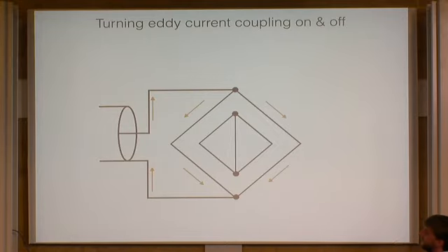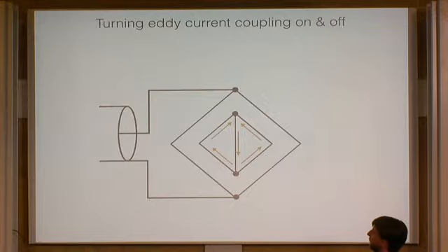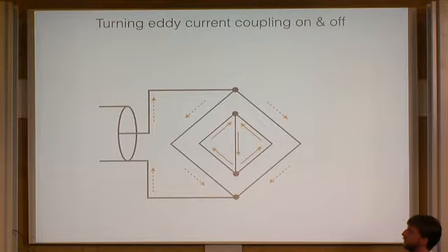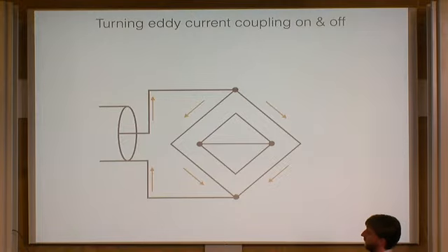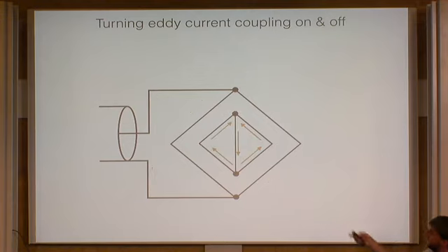Now, if you send a current through this loop, it'll go around the edges. As soon as you turn that on, that will try to induce eddy currents inside that floating circuit. It'll go like that. Alternatively, if you could magically induce a current in that floating circuit, that will induce eddy currents in the external field, which, if this transmission line is terminated with a resistor, say, would start to dissipate that electricity. But it's important how this circuit is oriented. If instead it was oriented on its side, you should actually get no eddy currents flowing, because now the net magnetic flux into this top loop is zero, whereas before it was non-zero, because they're oriented this way.